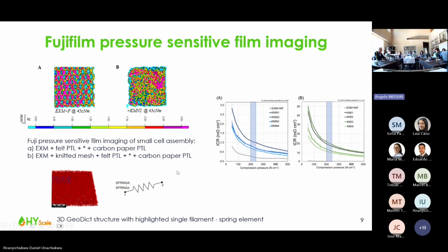The contact resistance is shown on the right side, and these values are quite low, in milliohm per square centimeter. In blue, the clamping pressure that is typical for a stack is visible. So the contact resistance between the stack materials is quite low. So we are not planning to really combine them because this would be a problem for the flexible element. But for stacking, sure, it's more complicated to have them separated.